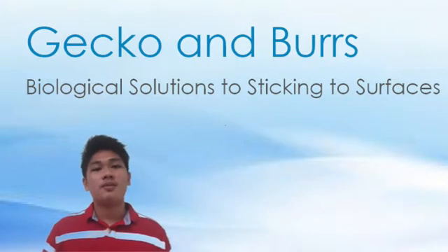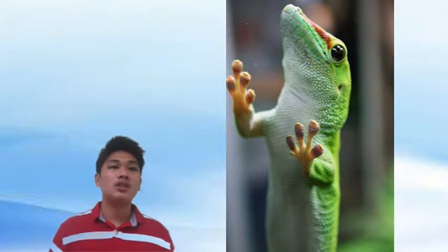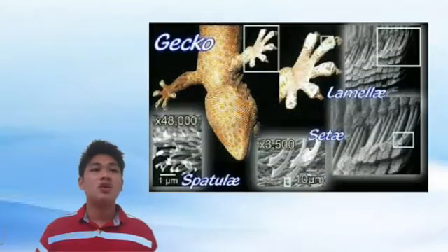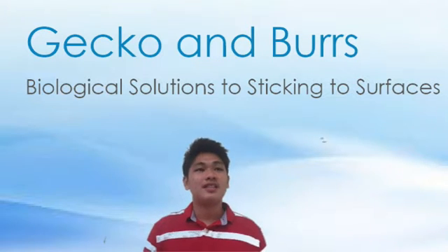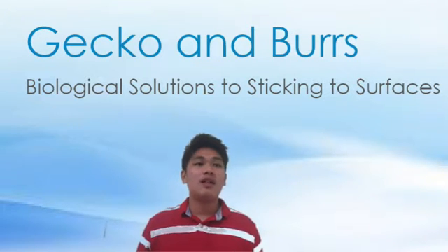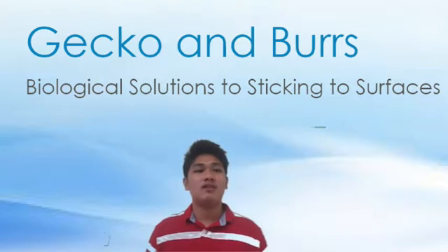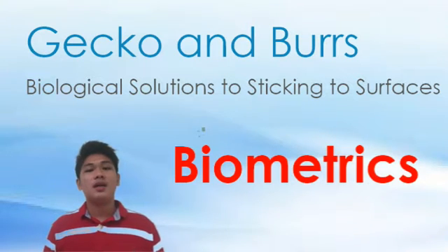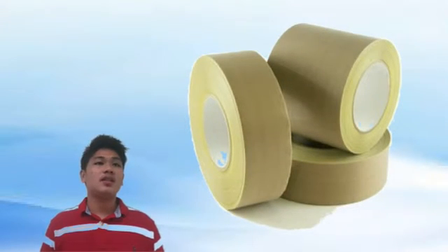Next one is gecko and its setae. Gecko lizards do not have suction cups on their feet but are able to climb up walls and stick to the ceiling. Setae is a toe pad consisting of hair-like structures. Adhesion strength is related to the polarity of the substrate. The more polar, the better. Next is the mechanism, Van der Waals force. It does not secrete sticky materials, but it can adhere to different surfaces. The biomimetics involving gecko lizards and setae includes new tapes that have been designed, developing dry adhesives to eliminate sticky residues left